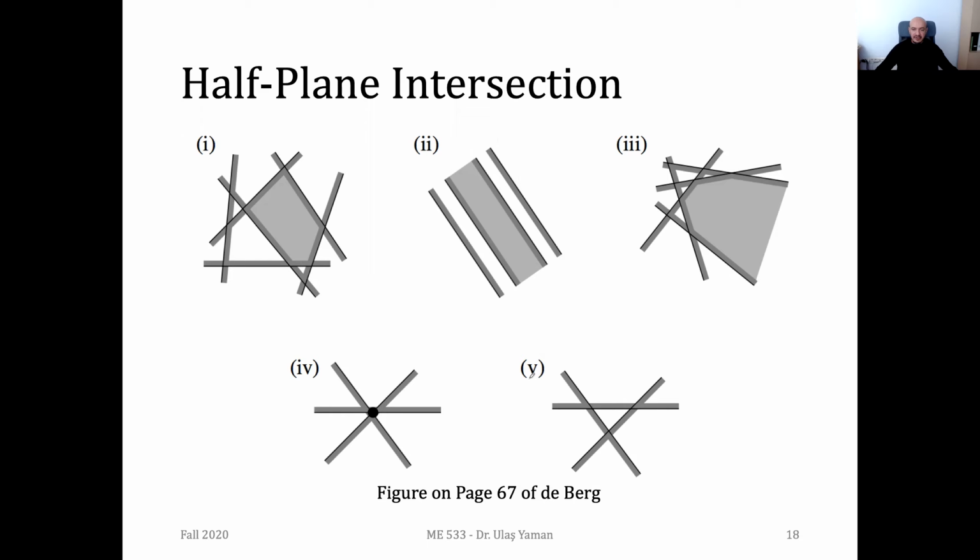And what about this one? We have, as you see, no intersection, so this is not feasible. If you come up with such a polygon, such a region, or you don't have a region actually, you can simply say that the part is not castable with a single mold.